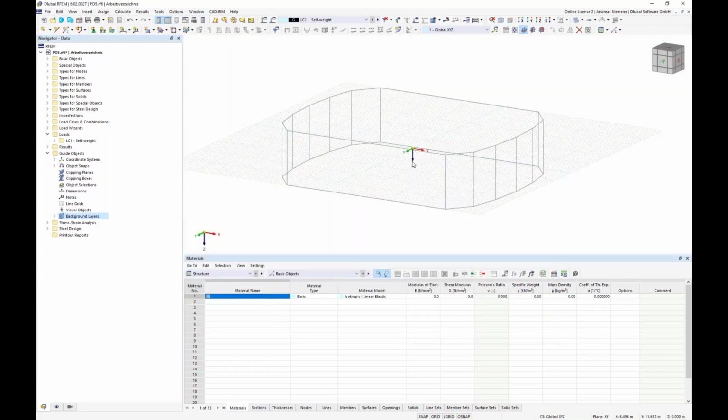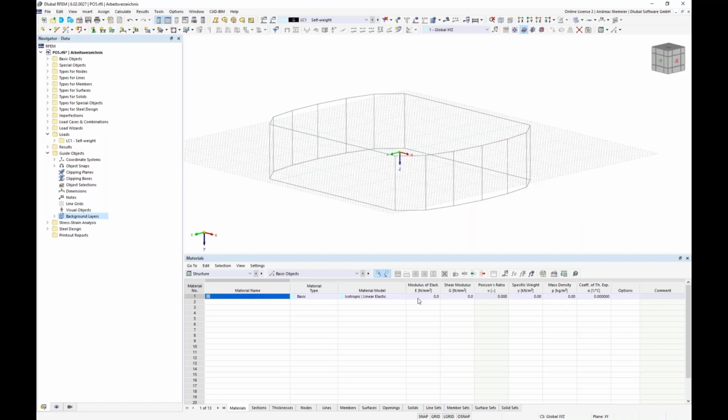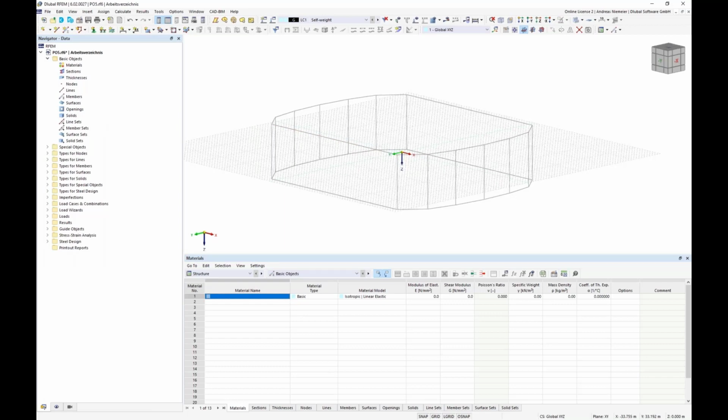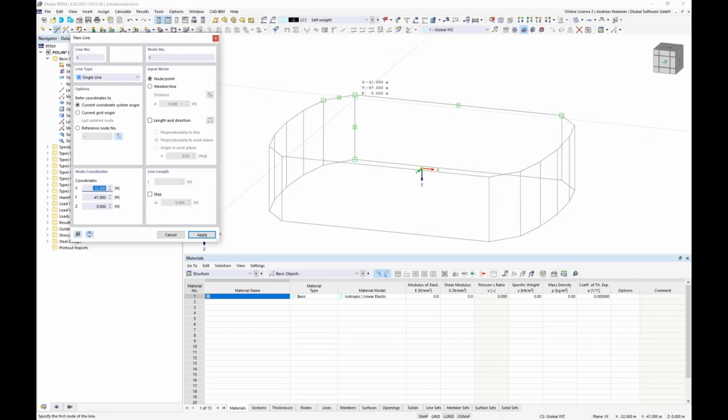So with confirmation of this item, we get such a line geometry in our RFEM, which gives us these basic geometries for our roof. If you pick on this element, you could assume it's lines, but it isn't. It's only the geometry you imported, but it doesn't produce line elements itself. We have to use these points to create them, but it will not create that automatically.